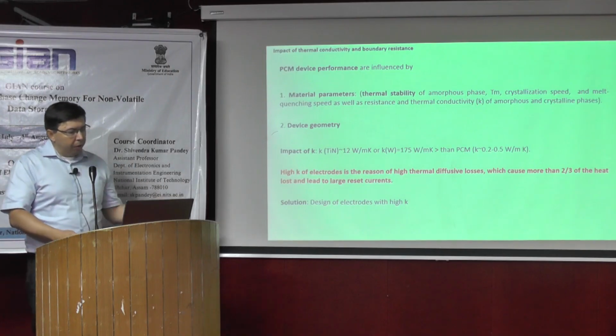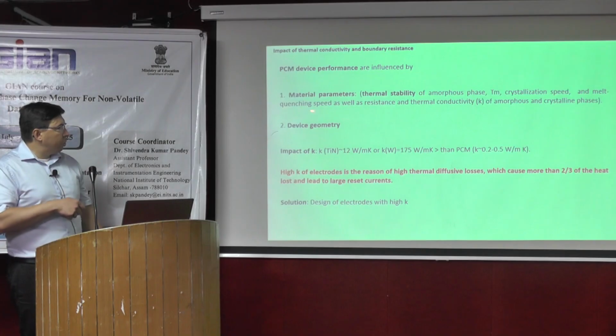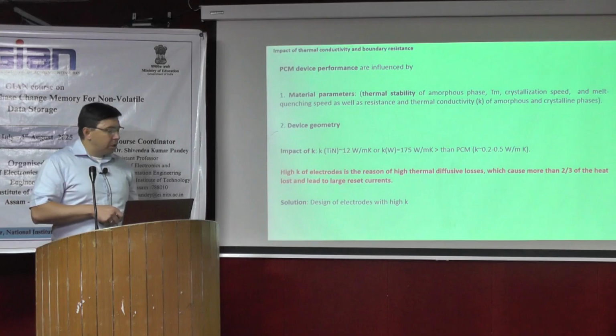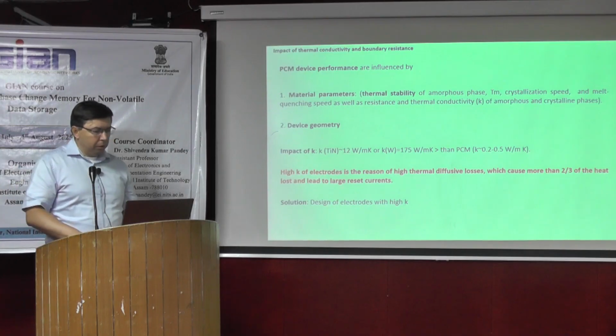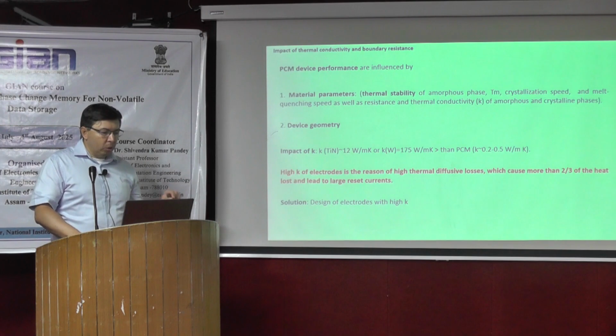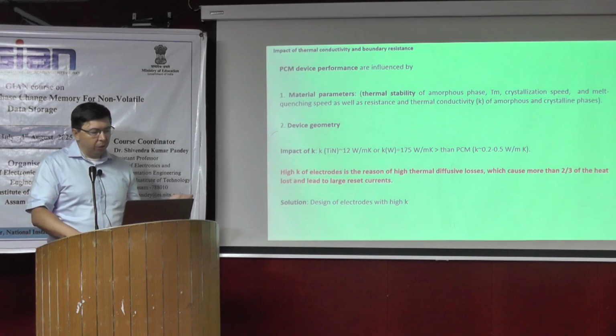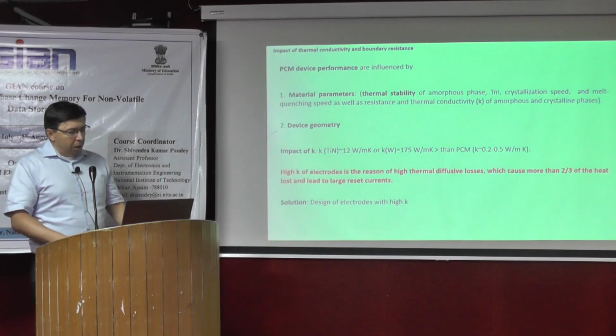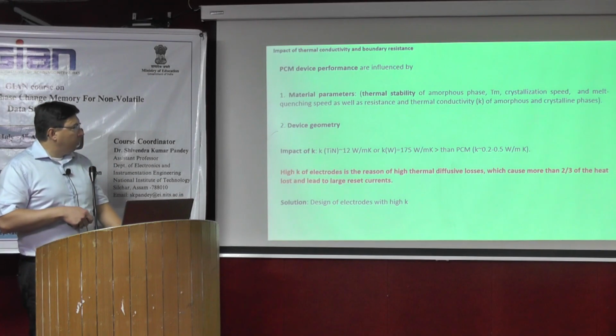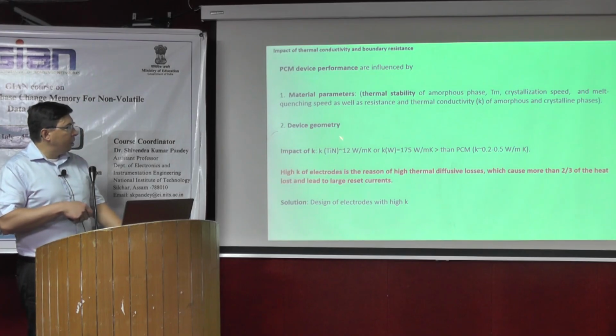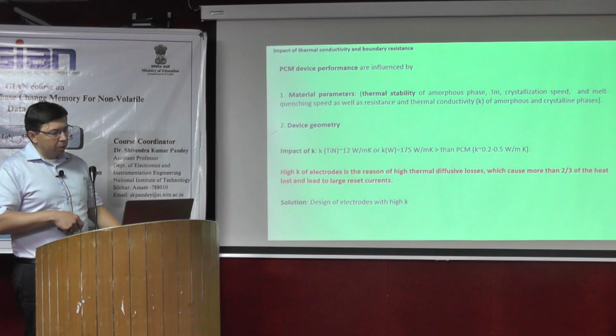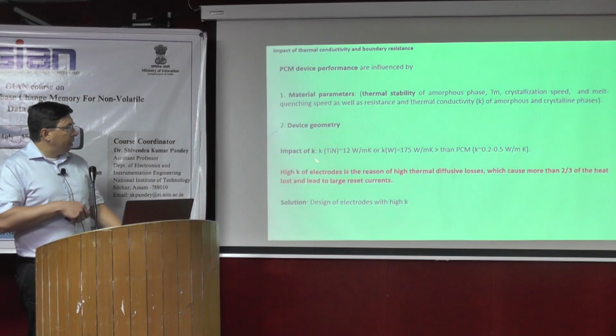I cannot consider everything, but one interesting consideration on the device side is how to improve the electrode materials. The problem of electrodes: standard devices use titanium nitride electrodes for switching, and they have thermal conductivity in this range.